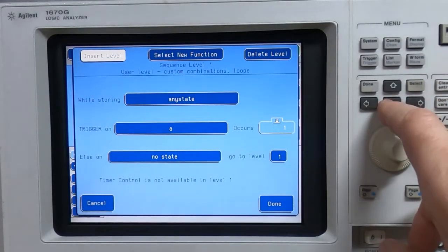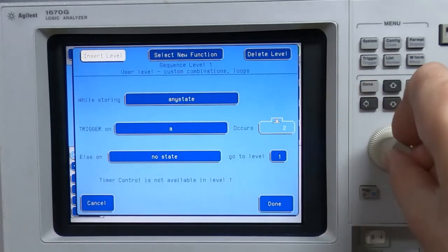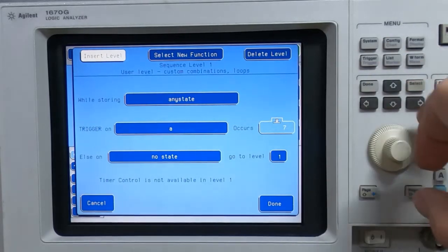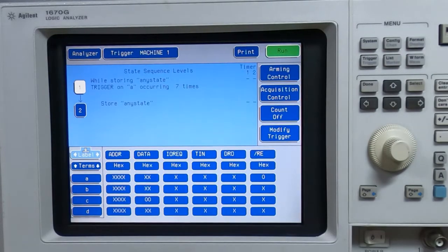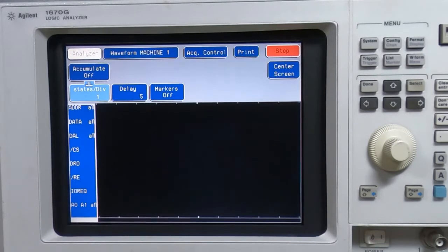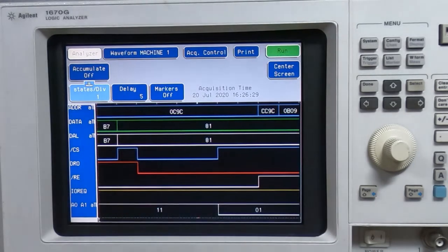So what we need to do is to change the number of hits so that we exceed 12 full clock cycles. So for example, if we go to 7, then that should give us a hit on the next data value being read from the floppy drive controller. So we'll rearm the analyzer. I'll press reset on the Wren, and what we're getting now is a value of 81.